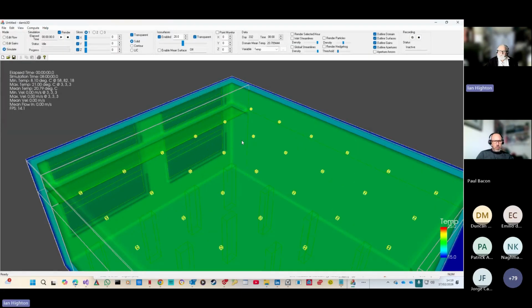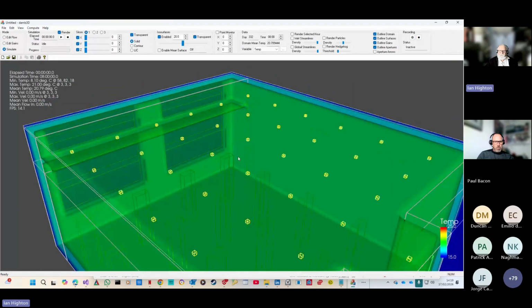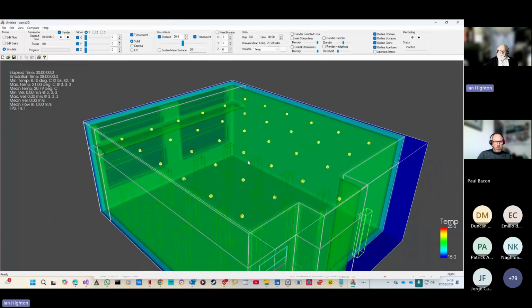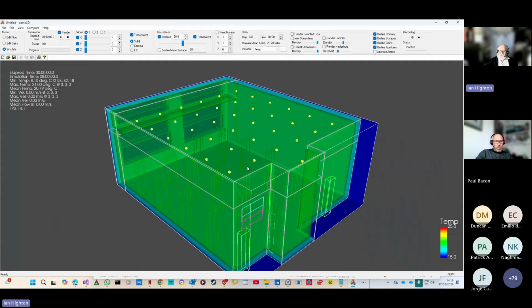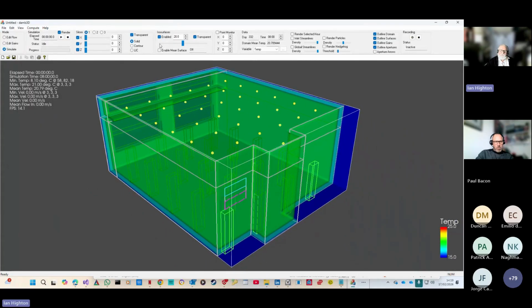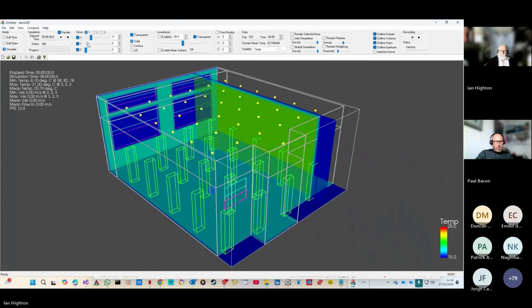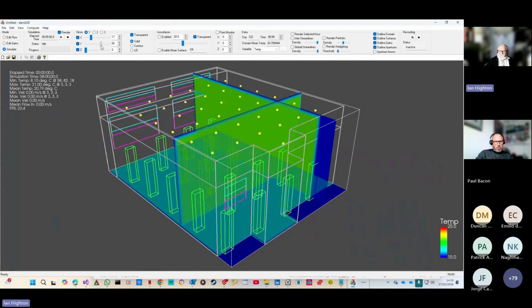Okay, so it's the usual sort of mouse stuff. You can spin the thing around. You can zoom in and zoom out and move it with the middle mouse button. So zoom's on the right button. I'm going to get rid of the ISO surface just to start with and just place some slices so we can see the results.